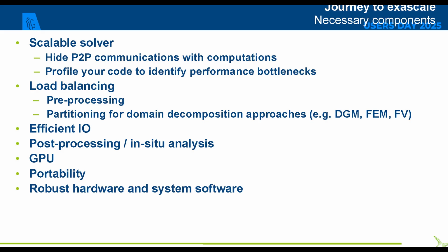So now I would like to share with you some of the necessary components, or ingredients, or bottlenecks at least, that I've been working on or I've encountered during my journey to, well, not yet exascale, but at least, let's say, to petascale simulation. So first, obviously, you need a scalable solver. I'm not going to provide all the key ingredients for a scalable solver because you know your code much better than I do. But usually, good advice includes to hide peer-to-peer communication with computations and also profile the code to identify performance bottlenecks.